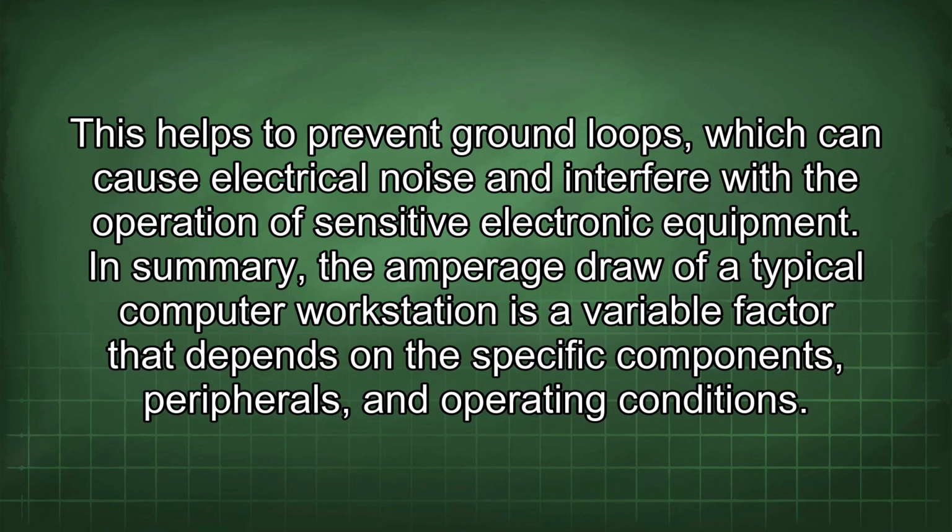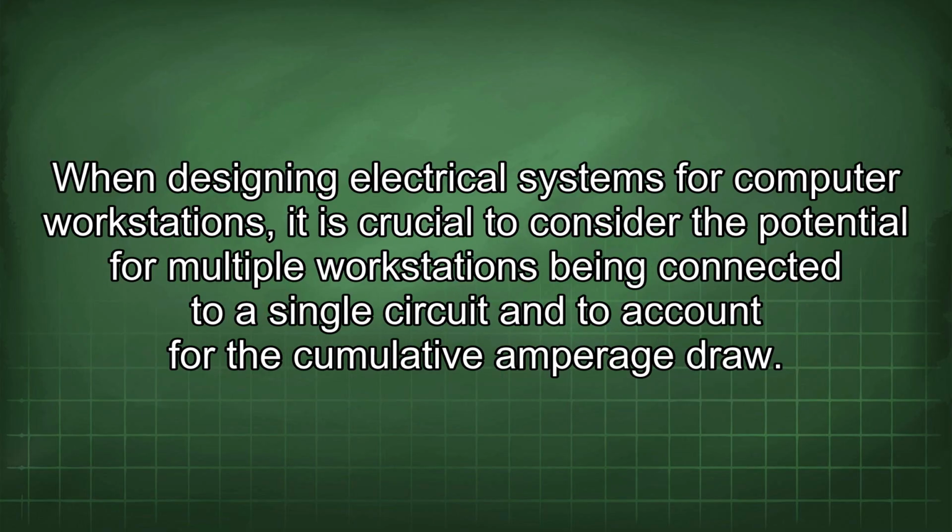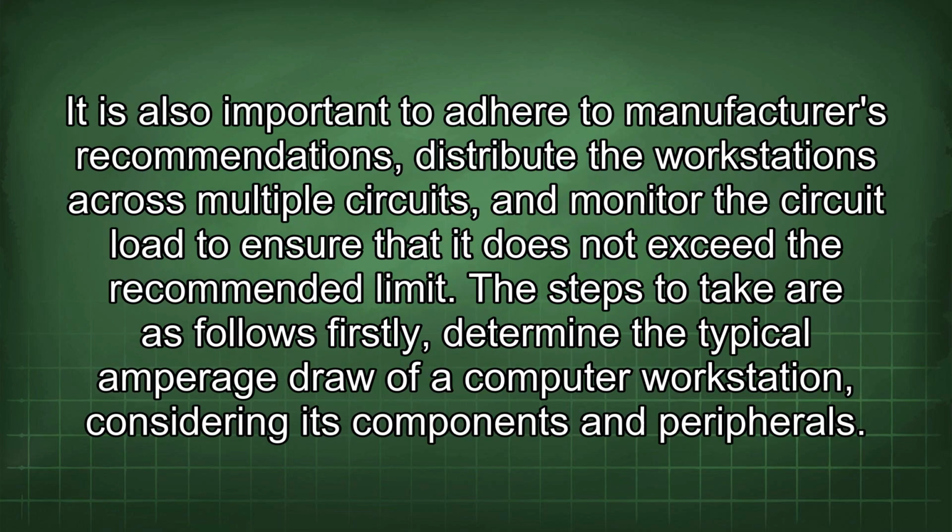In summary, the amperage draw of a typical computer workstation is a variable factor that depends on the specific components, peripherals, and operating conditions. When designing electrical systems for computer workstations, it is crucial to consider the potential for multiple workstations being connected to a single circuit and to account for the cumulative amperage draw. It is also important to adhere to manufacturers' recommendations, distribute the workstations across multiple circuits, and monitor the circuit load to ensure that it does not exceed the recommended limit.